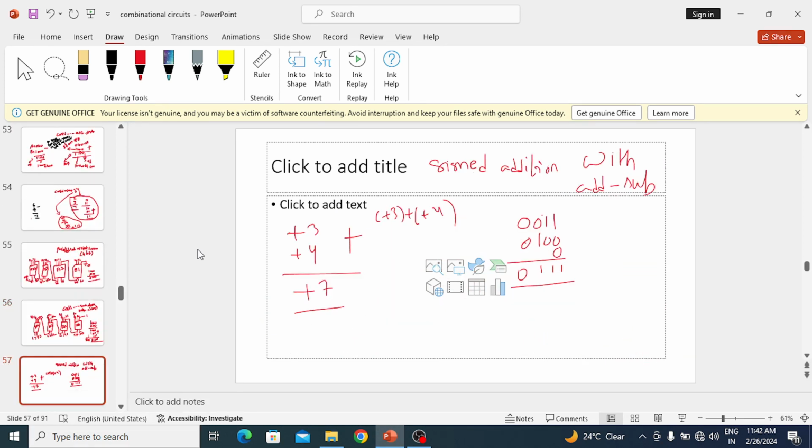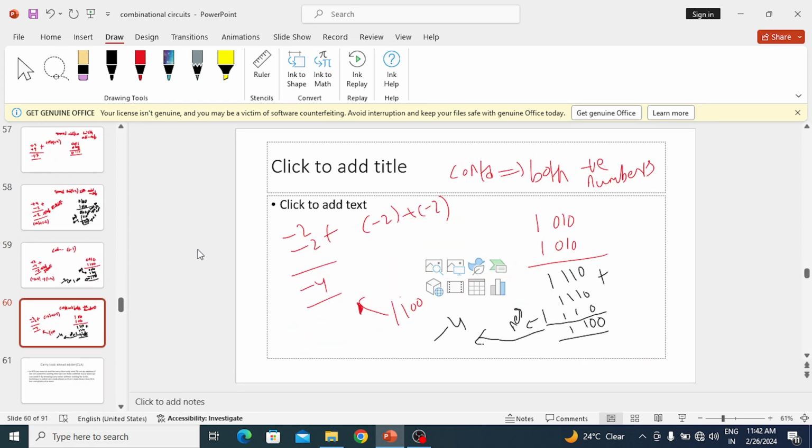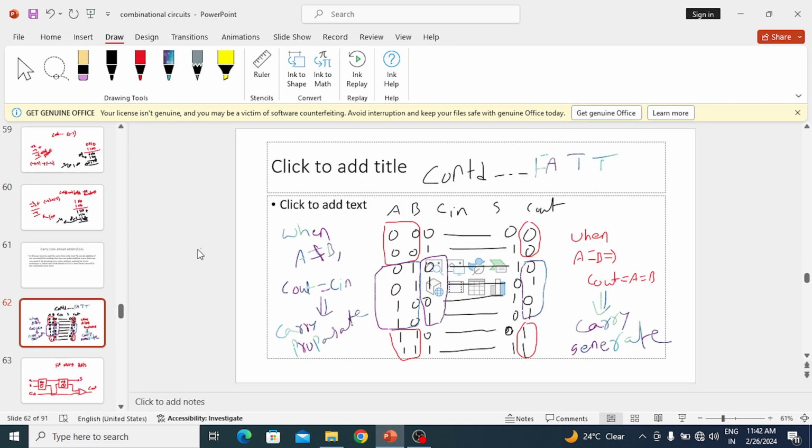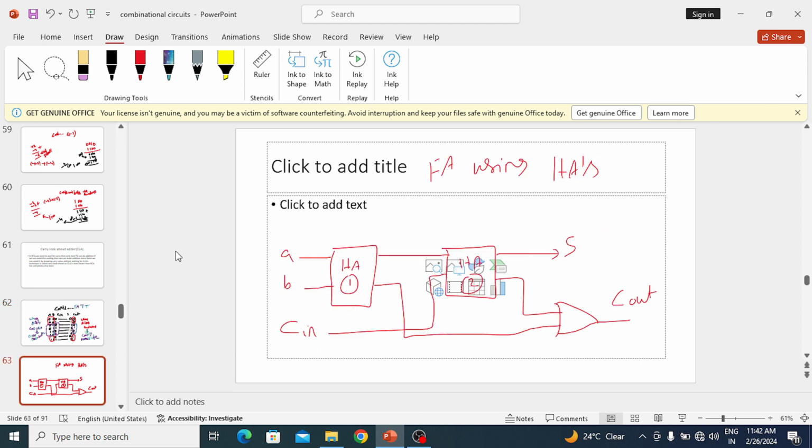So that is called carry look ahead. We are avoiding a waiting time, so we can make it faster. From this you understood carry look ahead logic, carry generate and carry propagate. Carry look ahead logic means generate and propagate logic. Now to design the logic circuit of a carry look ahead adder, we need some Boolean equations.